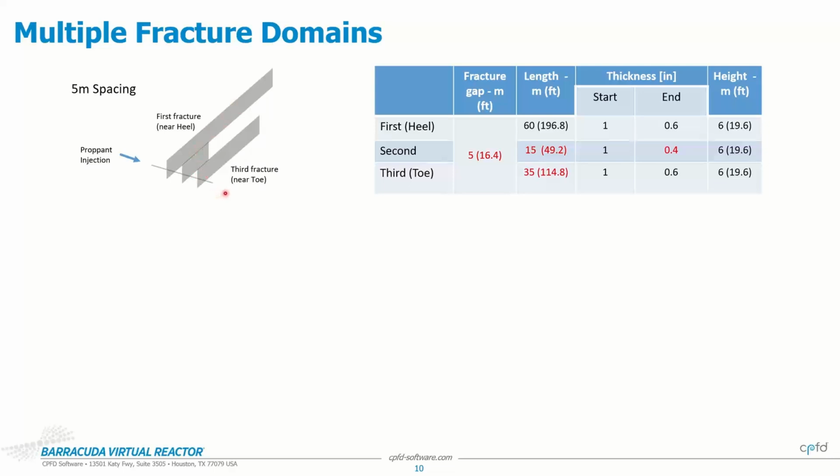And this is what I was referring to, a phenomenon known as the stress shadow effect. So what happens is basically, when the first fracture is forming, you're injecting this high pressure fluid, it essentially squeezes the rock surrounding that region, right? So the first fracture opens up, but it creates this extra pressure, or what is known as the shadow effect, on the surrounding rock. And therefore, the fracture that is immediately next to this is not as well developed, and so it is actually stunted in length.